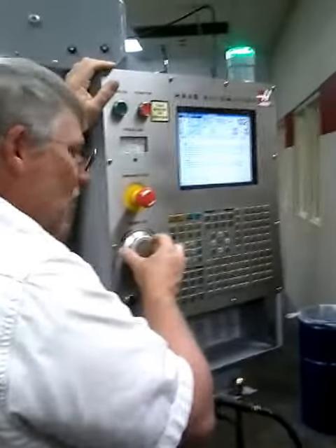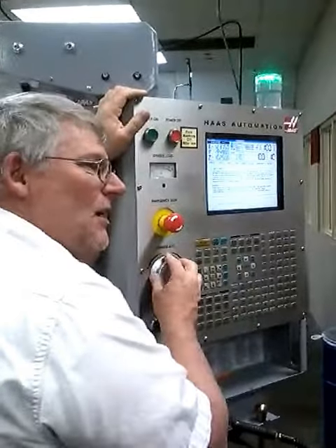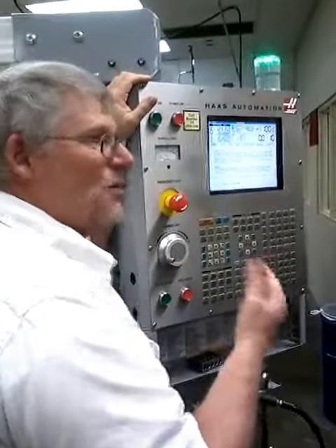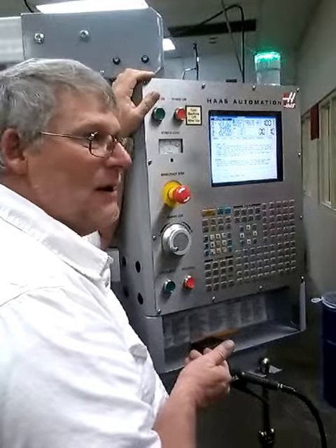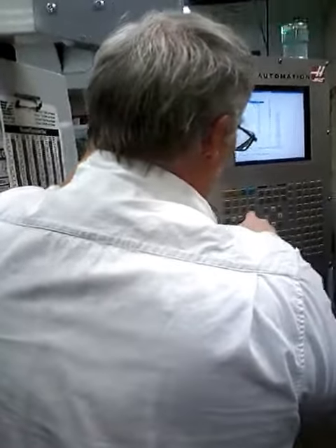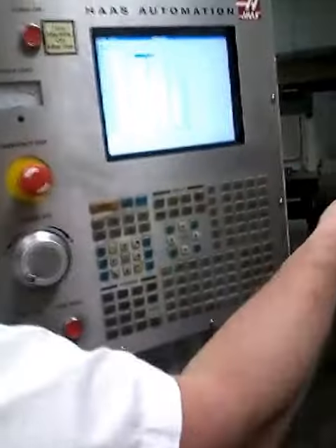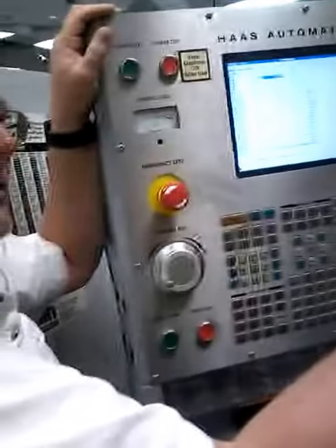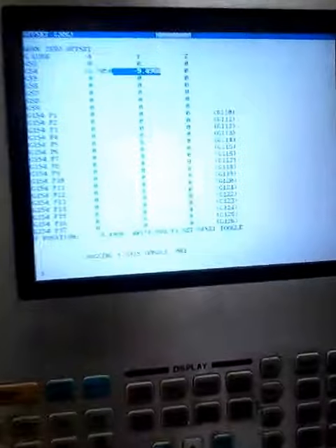So here I wasn't against it. Here I am against it. I'm within a thousandth, okay? At that point, offset, work offset Y, part 0 set. I need to go positive 100 thousandths, don't I? I simply tell it 0.1, right enter.